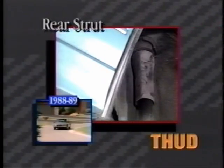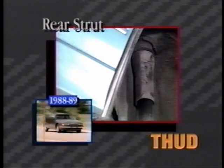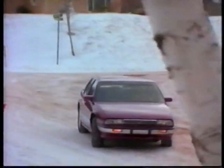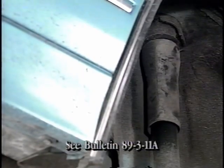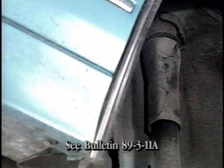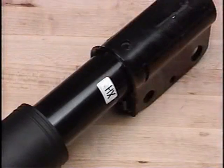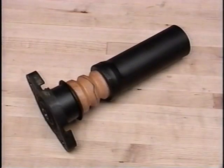On some 1988 and early 89 cars, a thud noise may be caused by the struts extending to the limit of their travel. The thud is most apparent when the car is turning sharply into a steep corner. This situation is not damaging to the struts. However, the annoying noise condition may be repaired by installing current design replacement struts. The newer struts provide about 3/4 of an inch of additional travel.